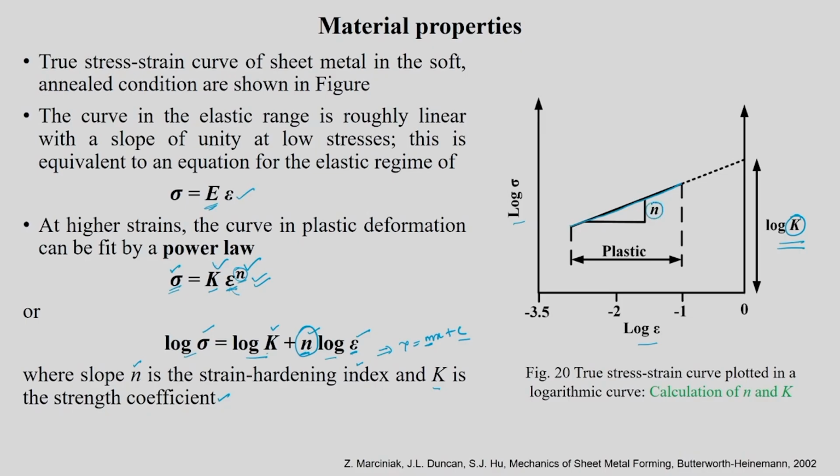So what you do is convert a power law into a straight line fit, and the slope of that line gives n, which is the strain hardening exponent, and the intercept in a way will give you K. I have clearly written that it is only in the plastically deforming zone. Once you have the true stress strain behavior: you have the load displacement graph, from that the engineering stress strain graph S versus E, and from there the true stress strain graph sigma versus epsilon.